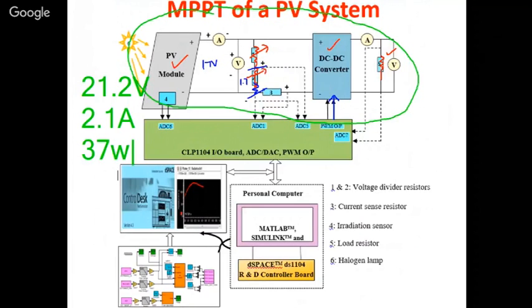So such a power circuit is there, and this control circuit, what is the voltage level of this control circuit? Mostly 5 volts, and you can go until 24 volts. Maximum 12 volts in many cases, and with an FPGA you can go up to 24, not more than 24. Just think when a high voltage from the power circuit flows into this, what will happen? It will get damaged. So you can have optocoupling and all these isolations there.